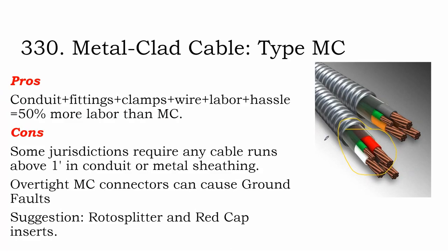Romex, for those AC circuits all throughout your house, has multiple circuits bundled inside of it. And so code has a section for single conductor cables. They also define multiple conductor cables. And then, the way it works is your multiple conductor cables, you're not pulling through anything. They already are kind of done for you. Whereas otherwise, if you're using single conductors and conduit, you build your conduit run and you pull your single conductors through it. So the question is, well, when do you use a pre-made cable and when do you not use it?